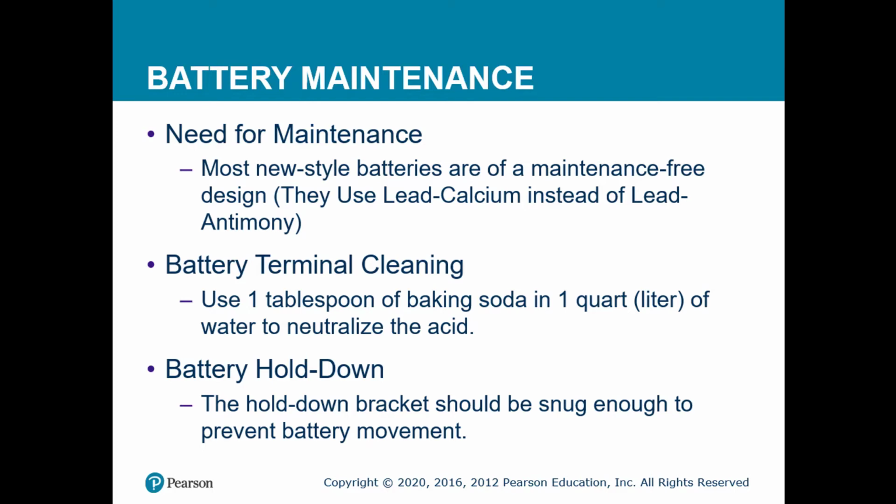Cleaning battery terminals is important. It says here to use baking soda. I'm usually going to use a commercial cleaner, but baking soda works great. It will work. And this is saying use 1 tablespoon of baking soda to 1 quart or liter of water to neutralize. Normally what I'll do is I'll dump in baking soda and make it kind of pasty. I'll show you a picture in a second.